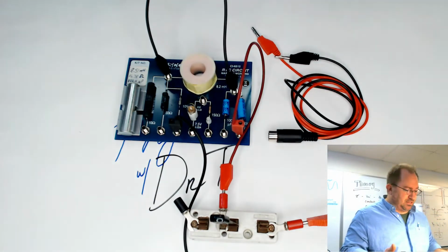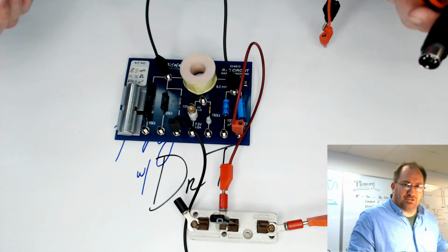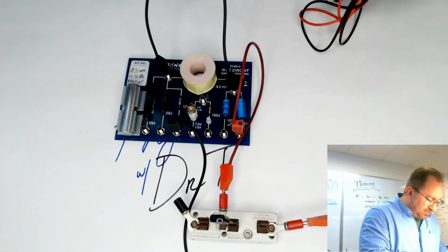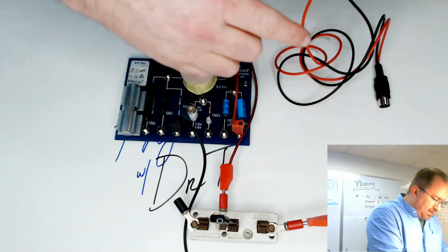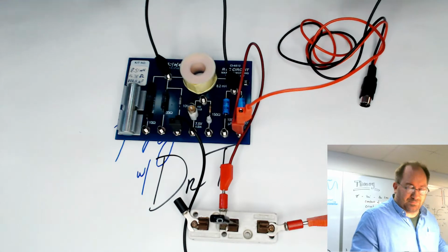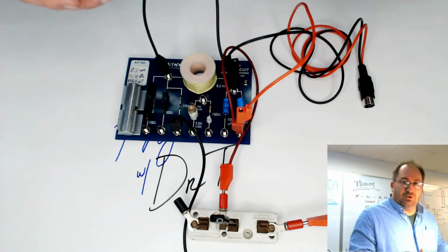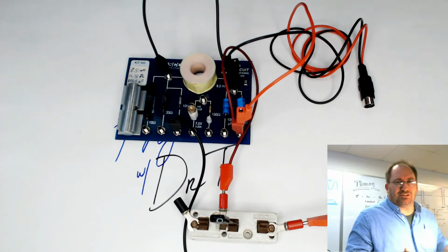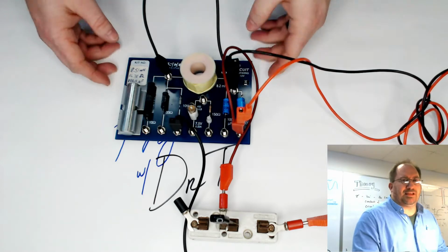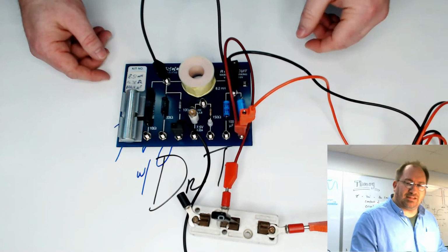You'll go through the settings that are in the lab manual, and finally you'll take the voltage sensor and plug this into your 850 adapter, and put the red on the positive side of the capacitor and the black on the negative side. Otherwise you'll get a negative voltage when you take your data, and there's nothing wrong with that. It just creates a little more challenge when you do the analysis. And that's it. This is what your circuit should look like when you are ready to take data.